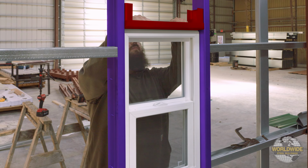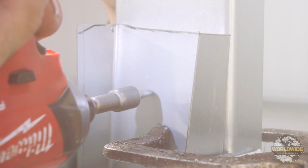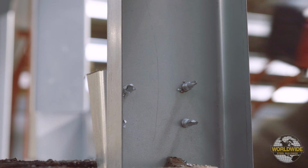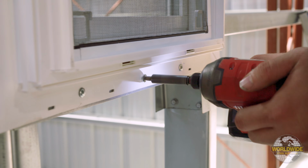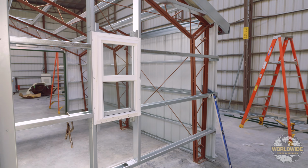Based on the window manufacturer's rough opening height requirement, position and attach your header with the tabs facing up in a similar manner as your sill. Your window rough opening is now complete. Follow the instructions provided by your window manufacturer for proper window installation.